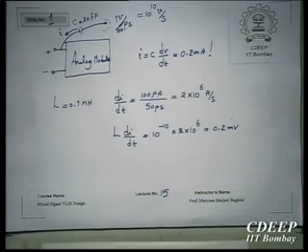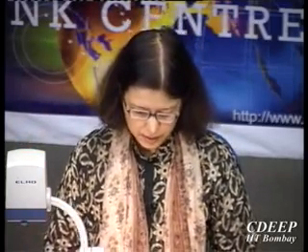In fact, it's very difficult to make inductors and transformers in CMOS technology. Therefore, inductive effects are much less, except one case, which is the bonding wires that go from the pad to the pin. That is the only part of CMOS technology which makes inductive effects very important and effective.